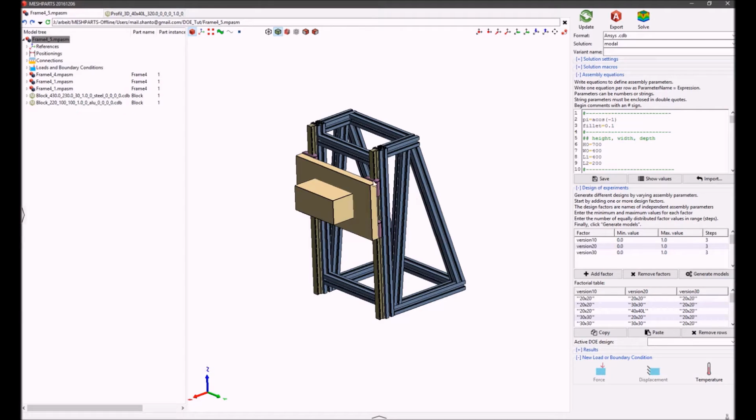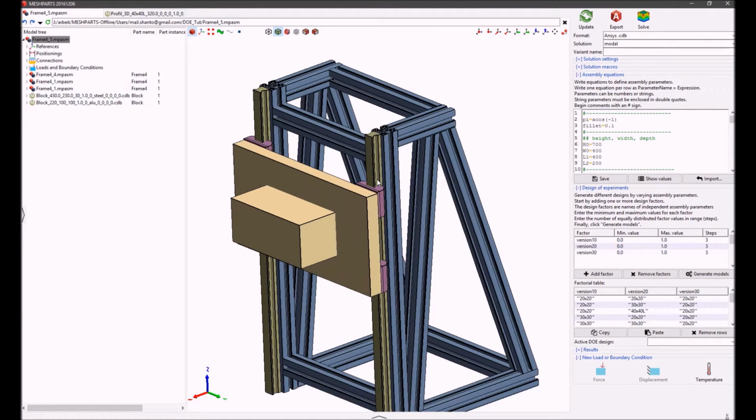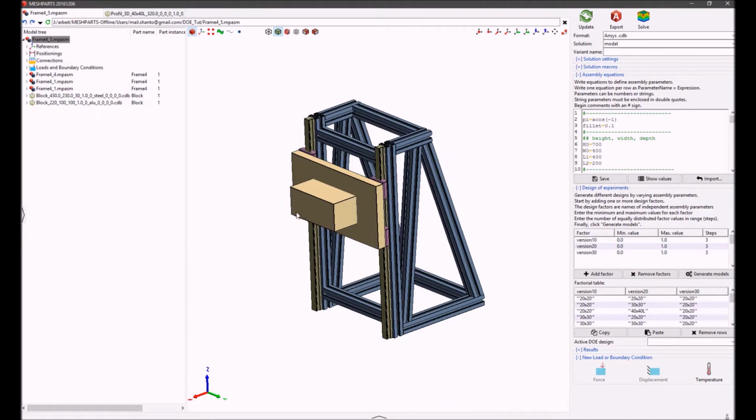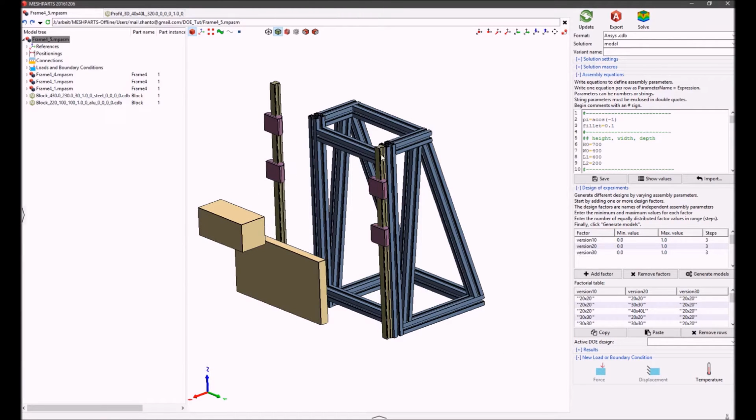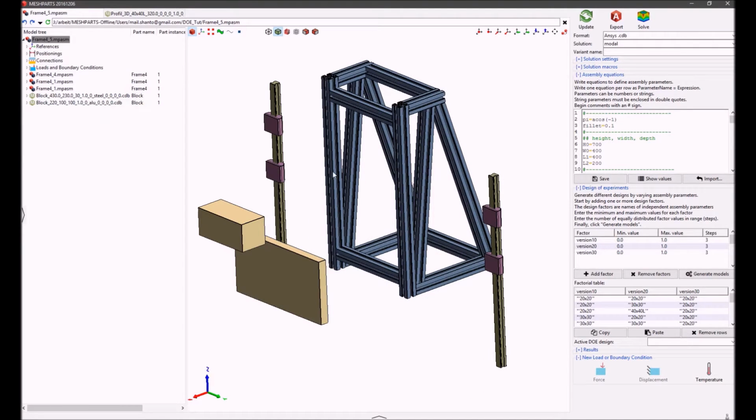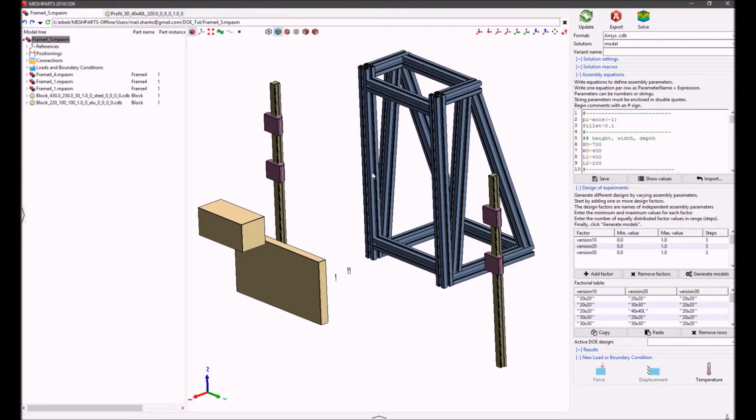The dimension of the assembly is parametric, so changing one dimension will automatically adjust the profiles and all other components accordingly. The structure shown has components and sub-assemblies. We see a block and a table component, a sub-assembly of wagons mounted on a rail, and a sub-assembly made with aluminum profiles. The wagon rail sub-assembly is used twice in the main assembly.